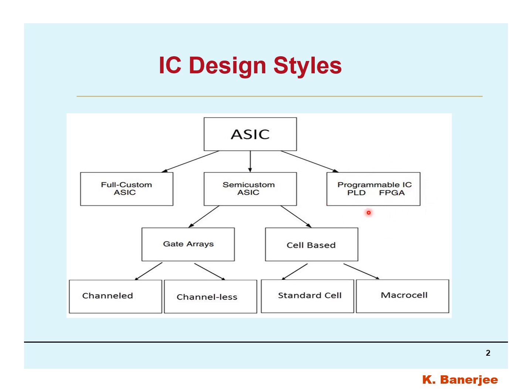This programmable IC designing can again be divided into PLD and FPGA that I will discuss in my next lecture. But in this lecture, I'm focusing on this full custom ASIC and semi-custom ASIC. So semi-custom ASIC can be again broadly divided into gate arrays and cell-based arrays. Gate arrays are divided into channeled and channelless designs, and cell-based arrays, majorly standard cell-based arrays, and there is another, that is macro cell, and I will discuss one by one.